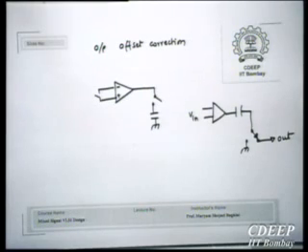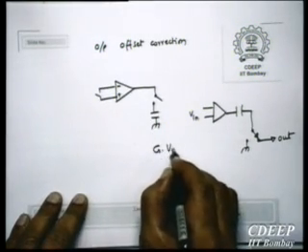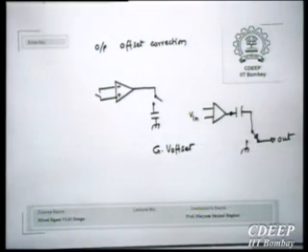Let's say that the gain of this is G. So when I applied 0 input value, what was the output value? G times V offset. This is where this output was resting initially. When I shorted the input, the output was resting at G times V offset.